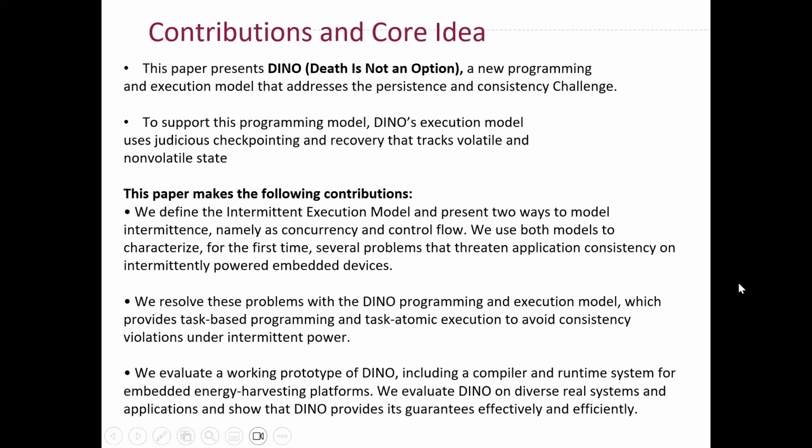Now, to support this programming model, DINO's execution model uses judicious checkpointing and recovery that tracks volatile and non-volatile states. We will discuss checkpoints more later in the slides, but this approach is different from previous systems that tracked only the volatile state and permitted consistency violations involving non-volatile state. By executing all instructions in its tasks, DINO guarantees that intermittent execution behavior is equivalent to continuous execution behavior.